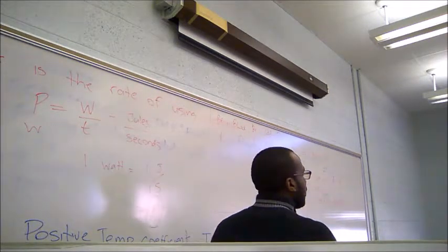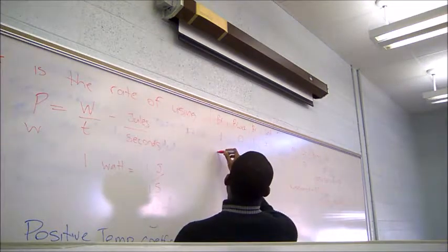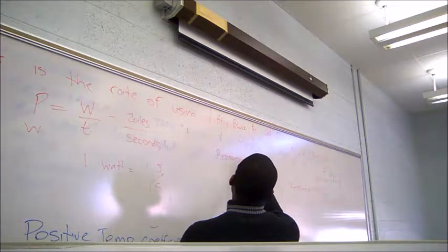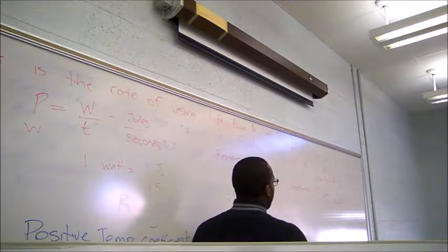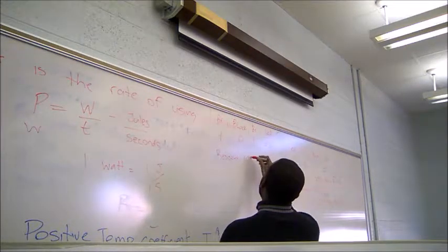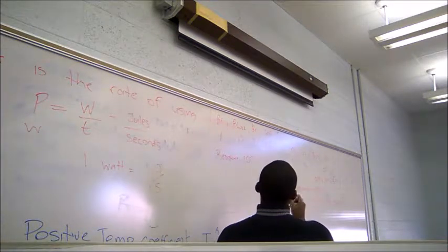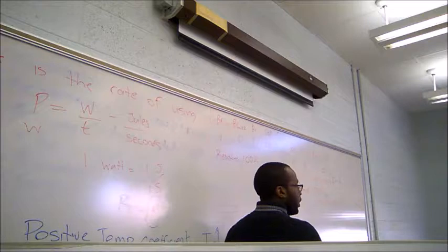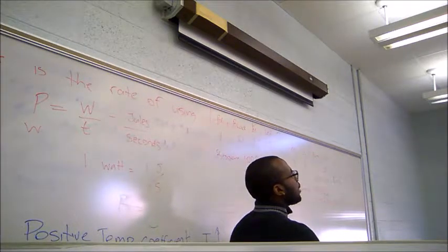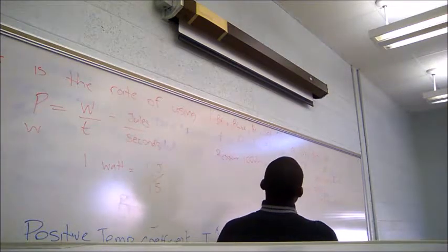Okay, all right. So based on our color codes here, what is our resistance? What is the first digit in our resistance? 1. What is the second digit? 0. How many zeros do we have? 1. So what is the resistance here? 100 ohms. We need to use the unit for resistance, 100 ohms. Okay? So now, based on the tolerance, what is the maximum value and the minimum value we should expect from our resistor?